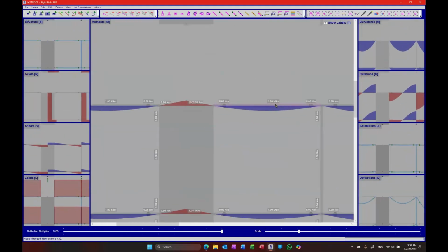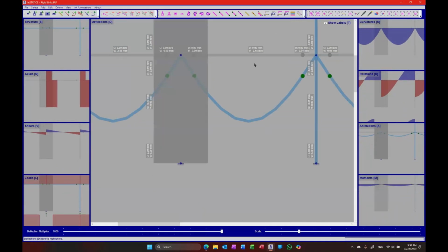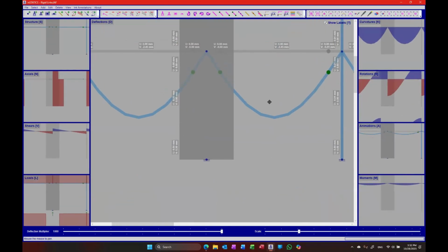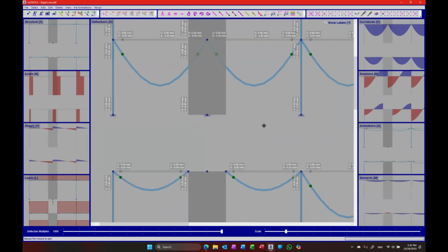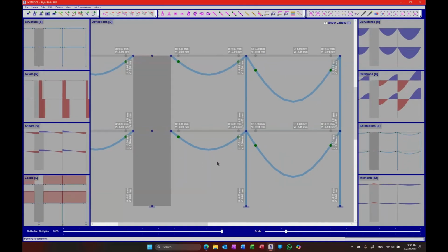You can see that it is 1 kilonewton. That's 50% of a difference. Very big difference. And in deformation side, I'm sure it's much more. See 2.45 millimeter, and it's only 1 millimeter. That's a 100% of a difference, right? So we have to be cautious when we're designing our structures. And one way of simulating these closer or more realistic behaviors is to use these rigid links.